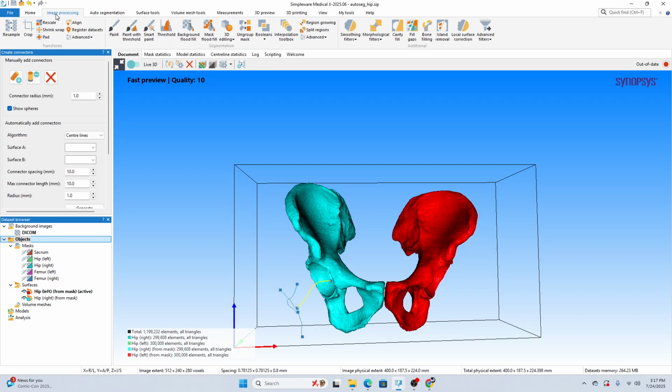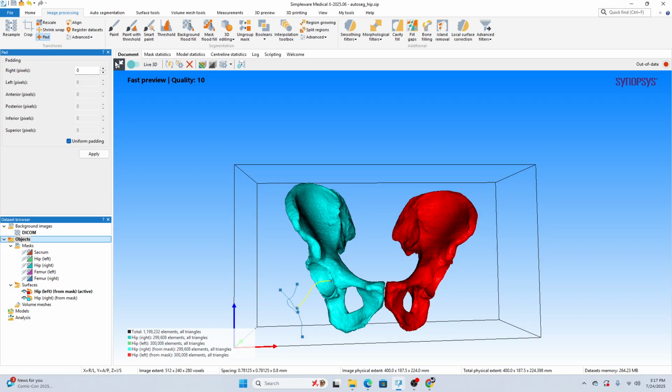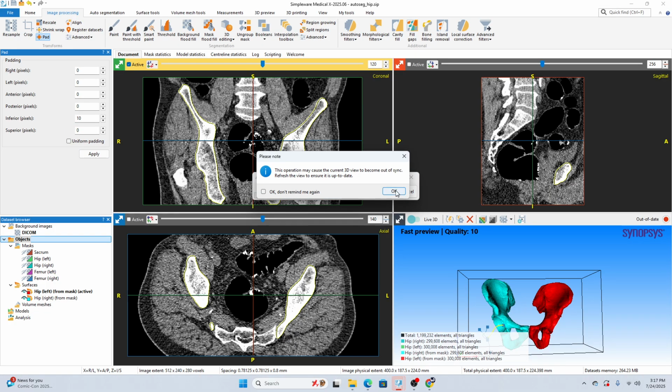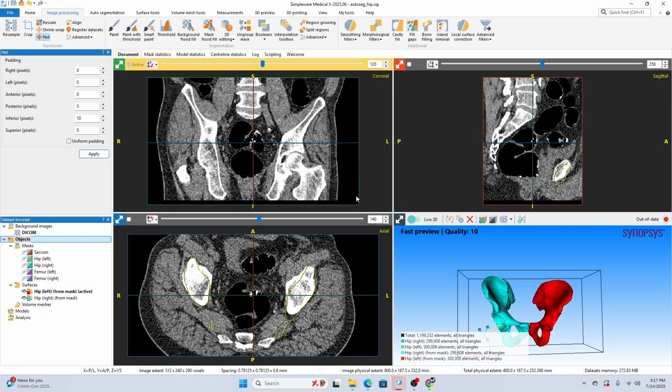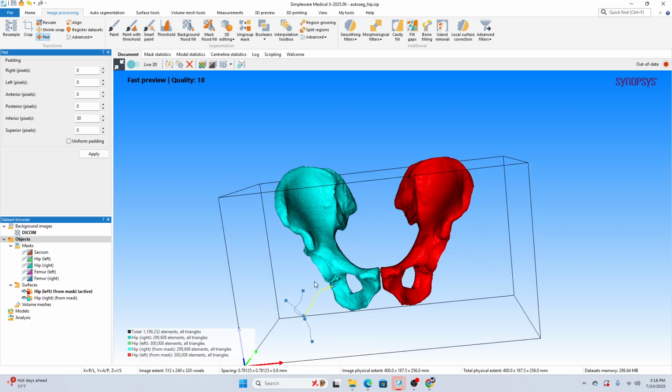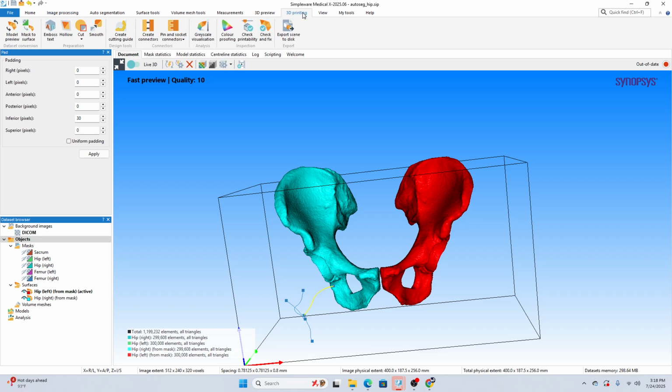One more thing we can do is increase the pad size in this direction. So we'll just click over here on padding. I'll increase in the vertical direction by 10 pixels. I'll increase a little bit more, around 30 more, to satisfy my requirement. I have done this because we also have another approach, a primitive, to create a primitive base structure for the 3D printing.